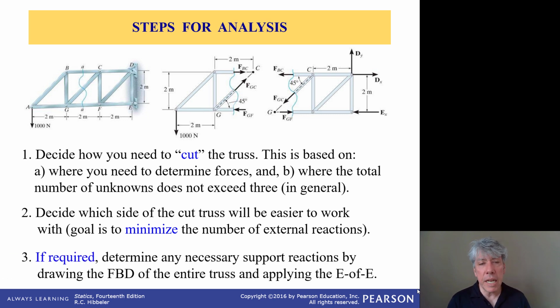Finally, if you need reactions, which you don't always, but if you need reactions, draw a free body diagram of the whole truss, get those, and then go back to your method of sections. Notice in this particular example, there's a left-hand side of the truss and a right-hand side. The left-hand side has an externally applied load, whereas the right-hand side requires analysis of the reactions.